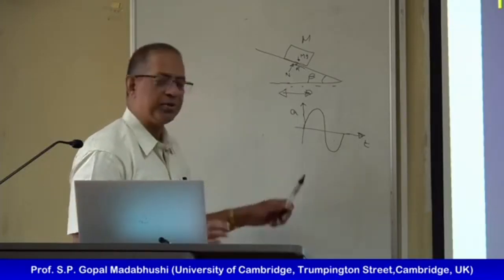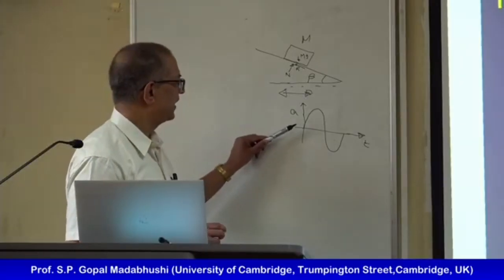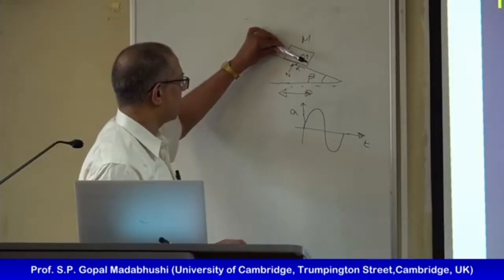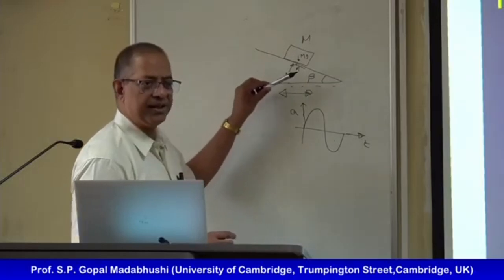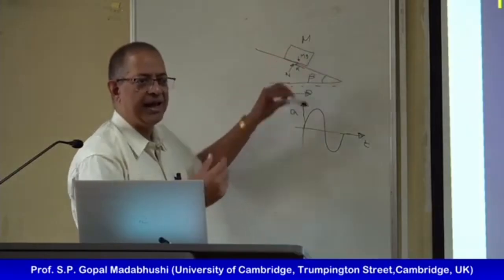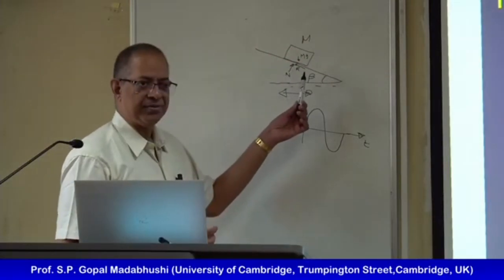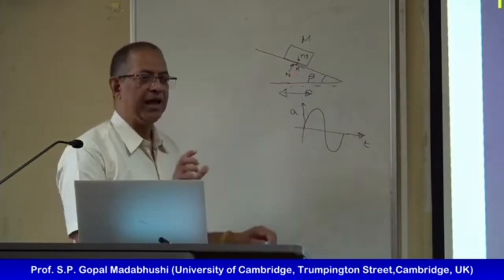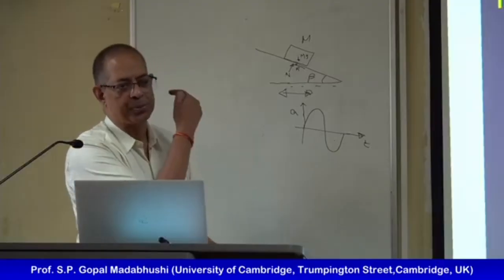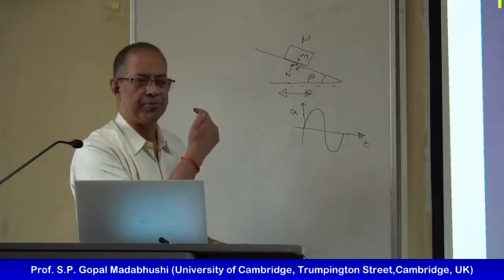Okay, good. That is one answer. If I shake this strong, I'll have the block which wants to slide down, but it's being held by the resistance force. If my downward acceleration times mass, if that force is bigger than R, then it will slide, right? In that first positive cycle. But in the negative cycle, the block is being accelerated upslope. If my pulse is big, it can also slide upslope, right?